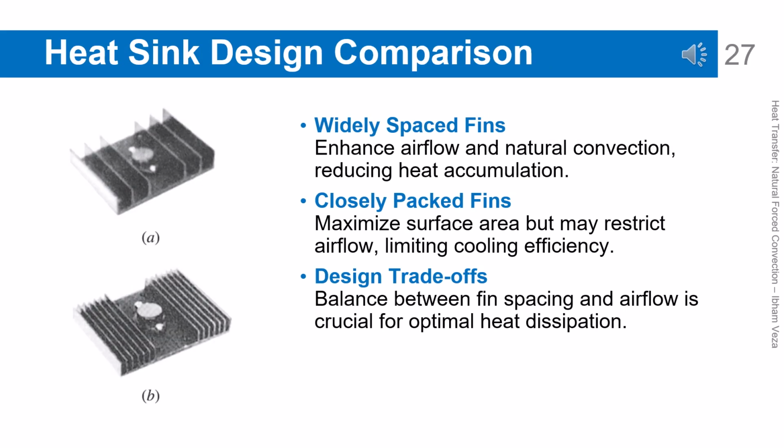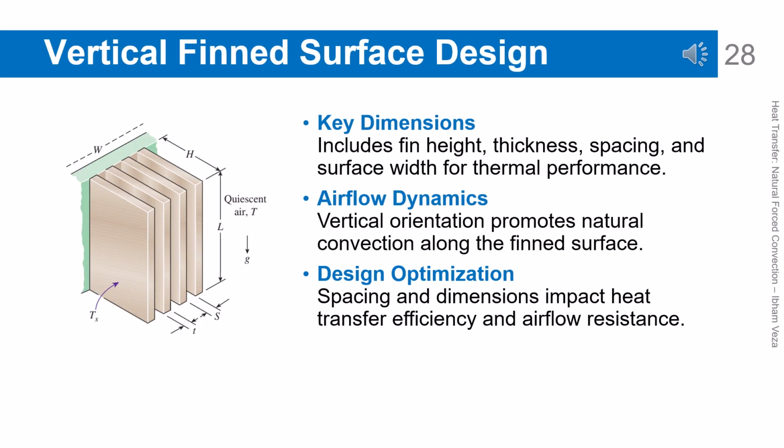Heatsink design comparison. Widely spaced fins allow air to flow more freely. Closely packed fins increase surface area but can restrict airflow. This flow resistance can actually reduce cooling effectiveness. Therefore, fin design always involves a trade-off between surface area and flow accessibility. Optimization does not always mean adding more fins.